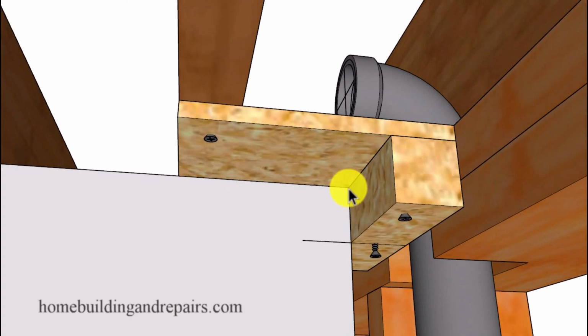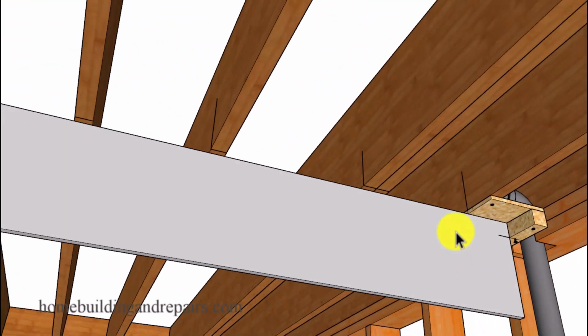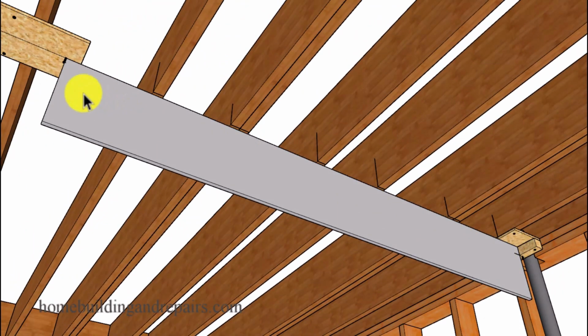Now I'm coming down 1 3/4 inches, and the reason for that is because I'm going to be going back 7 feet. And if I wanted 1/4 inch drop and a 7-foot horizontal measurement, I'm going to multiply 1/4 inch by 7. And that's going to provide me with 1 3/4 inches or 1.75 inch drop.